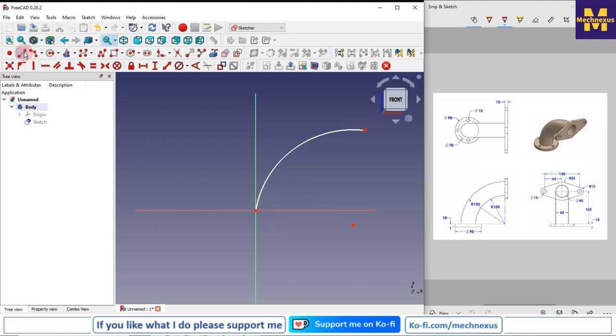and I will draw a construction line. To make it construction, I will select it and click on the construction geometry, and now I will select this line and arc, and I will make it tangent.